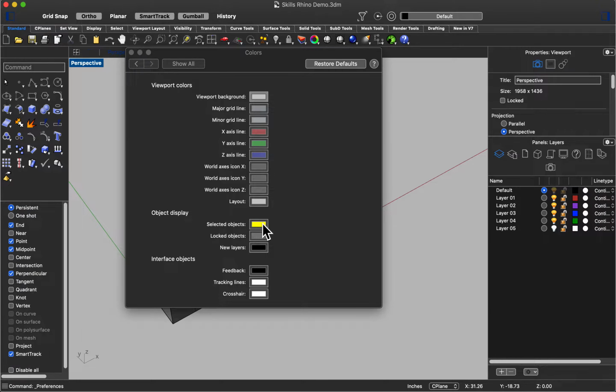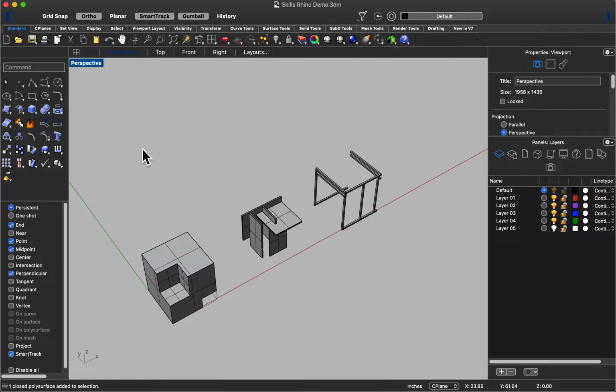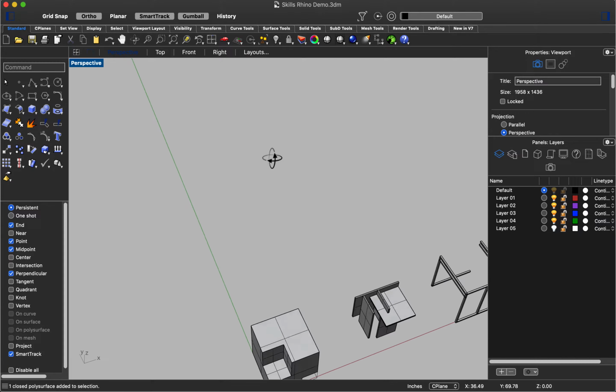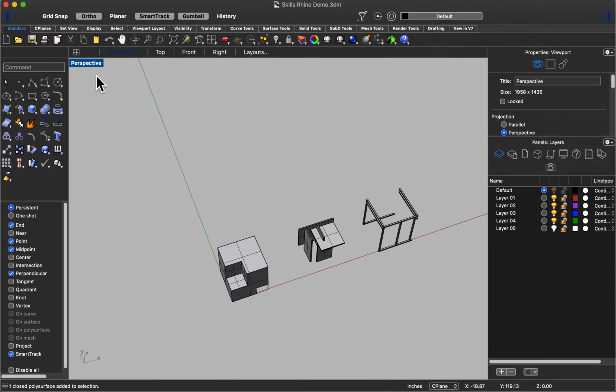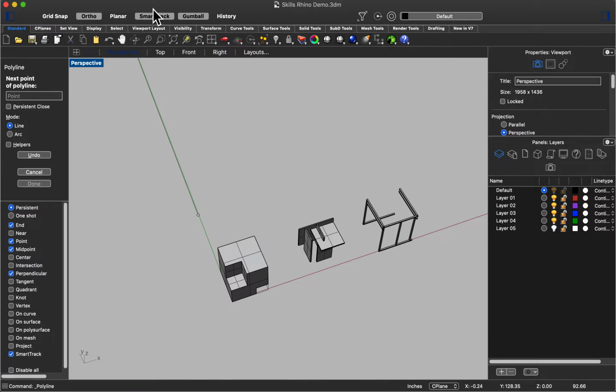And similar to how we've been learning about line, plane, and volume in Studio, lines, planes, and volumes as well as points are big parts of Rhino modeling. And so basically, when drawing, you're going to be using lines a lot of the time. And if you have your settings set to be perpendicular and ortho and on ortho, that's probably really good for this exercise. You're going to be snapping either at 90 degrees in any case.